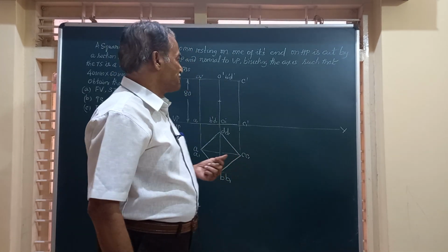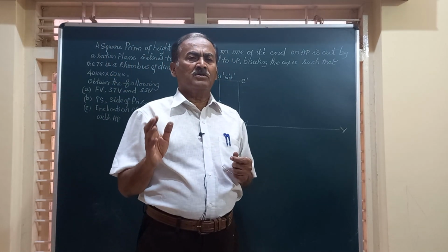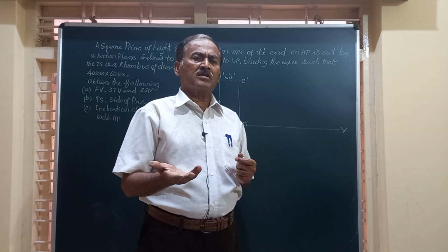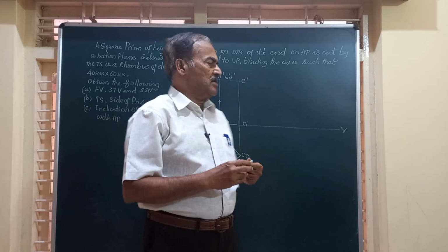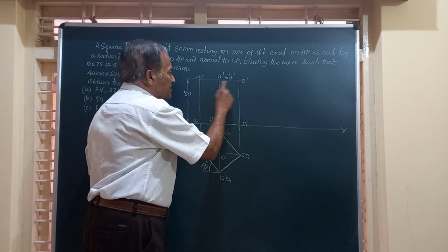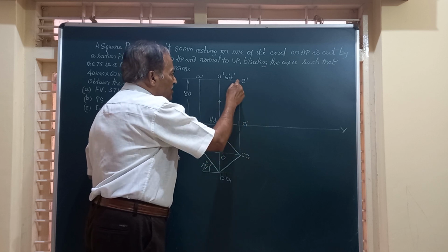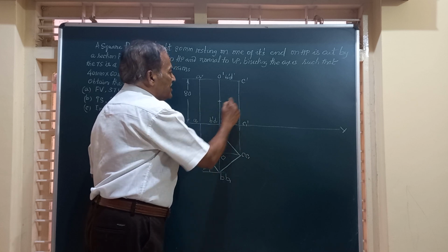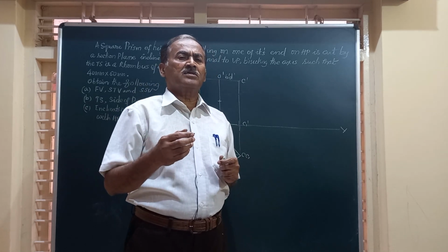That's not given. But remember, friends, whenever any of the prisms, whether square, rectangular, hexagonal, pentagonal, or a cylinder, which have a uniform cross section throughout their height, are cut by any section plane between the top surface and the bottom surface, it could be cut by a horizontal section plane or a section plane passing like this, or some section plane passing like this, the whole top view of the solid gets hatched.